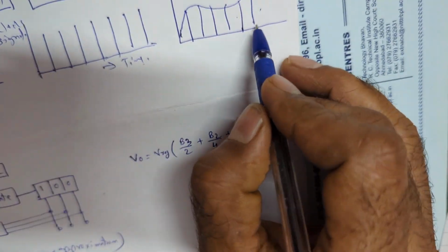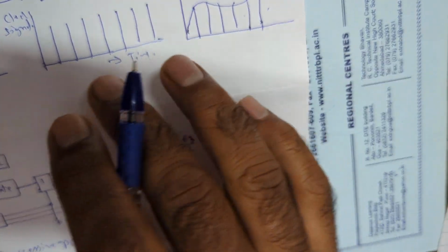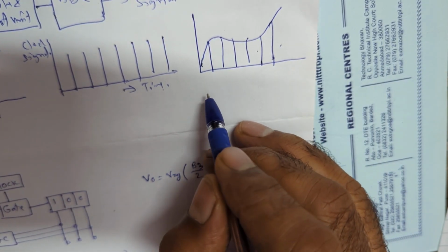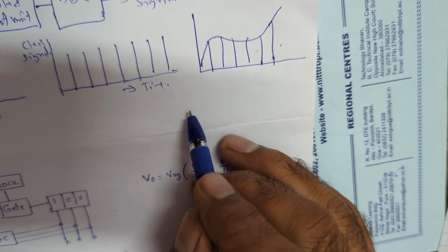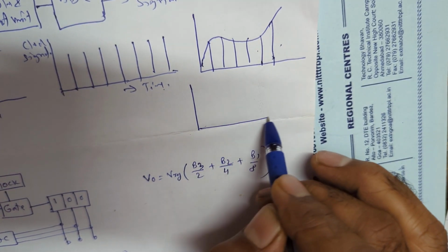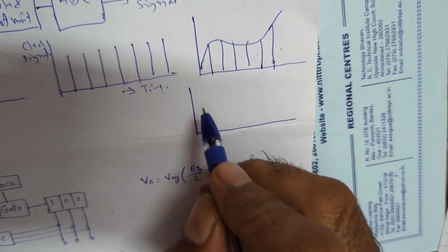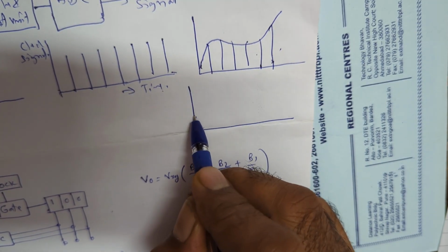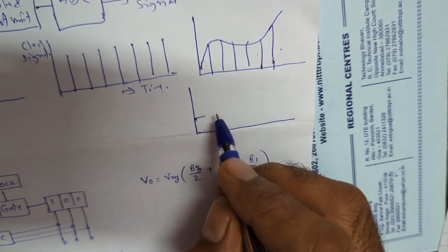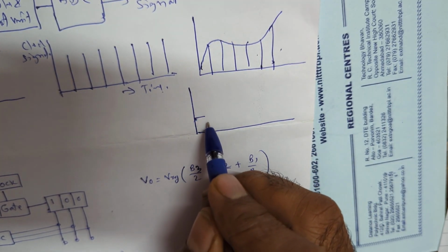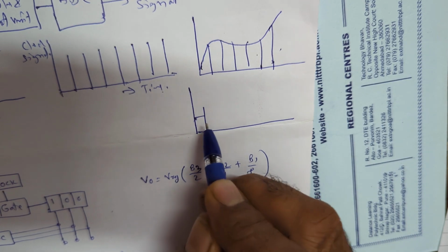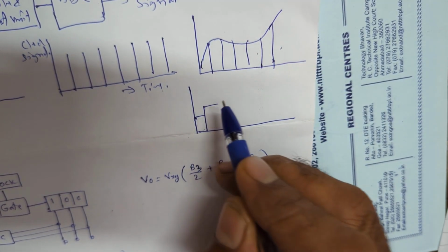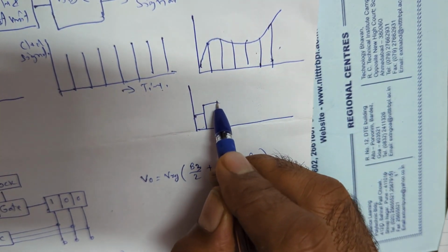And the sample and hold unit is a circuit which consists of capacitor and switches like transistors. You get the output which is held for that period of time. Suppose say this is the input. So the signal is held by the capacitor. The charge is held until the next signal comes. The next signal comes here. Then it is again held for that period of time.